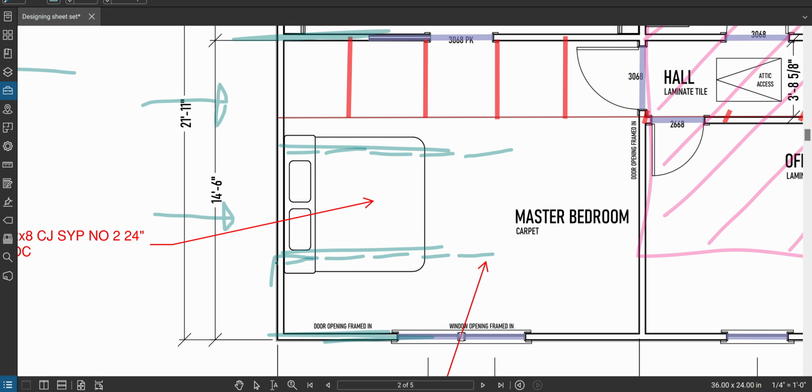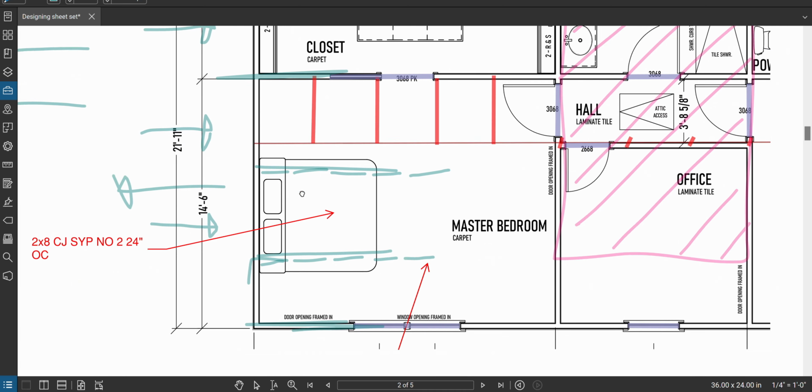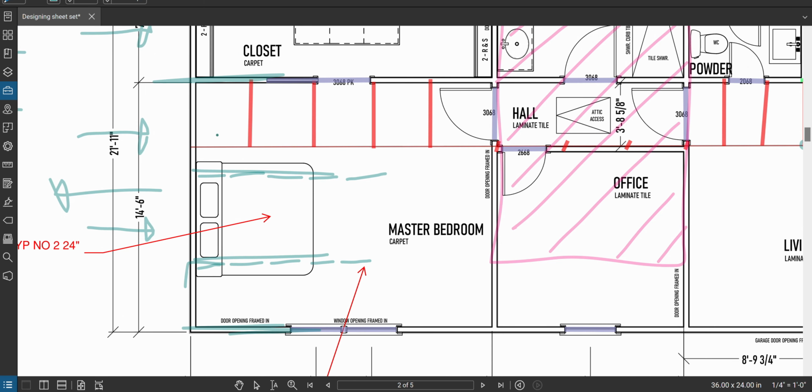You're going to strap it down so that it also provides strength against suction when the wind is pulling the wall this way. But you're going to do that. You're going to block into the ceiling. And what that does is use the ceiling diaphragm, which, when the house is built, is actually quite a stiff structure, right? I've got the 2x6s that are creating the ceiling joists. I've probably got a board running across them to space them out and keep them stiffer together. And I also have them all nailed together with sheetrock. Sheetrock can be considered a structural material, so it's stiffening this whole diaphragm.